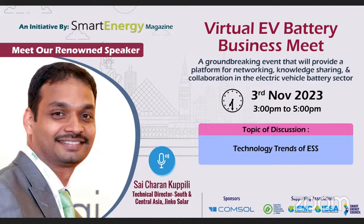Yeah, absolutely. You rightly said, if capacity is being increased just by increasing the cell volume density, it can definitely go even up to a 4.2 megawatt hour solution with the same container. What we are working on, specific to this 5.02 megawatt hour, is a combination of cell volume density and reduction in the spacing within this 20 feet container. The spacing now considered is close to around 1.2 meters. This probably can even work at 0.8 meter spacing of these four blocks.